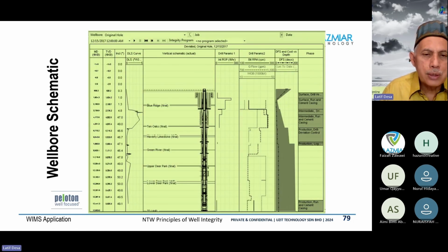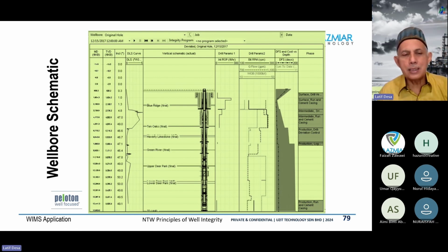Okay. Of course, in the drawing of a well cell, there must be a proper drawing, which is telling you 1,000 stories. So this will show you the elevation to your heli deck, your working level, and then you have your wells and your casing schematic, and they will show you the cement top here, and then normally they will show you the temperature. Normally they can have some logs that will record the temperature gradient. And all these other parameters of the well can be plotted in the well. You can recall those data when you want to do any jobs for this well.